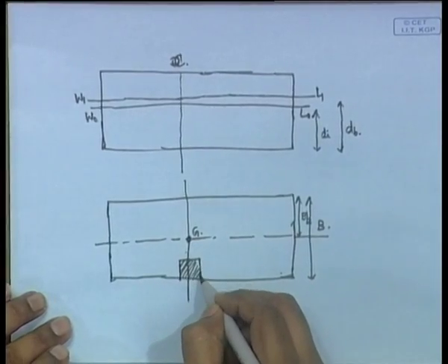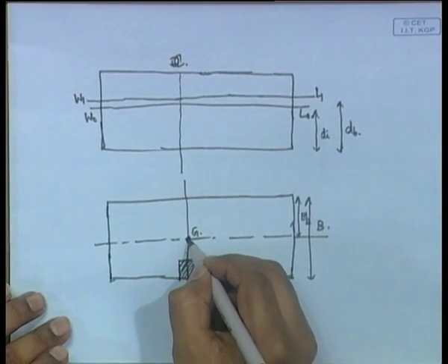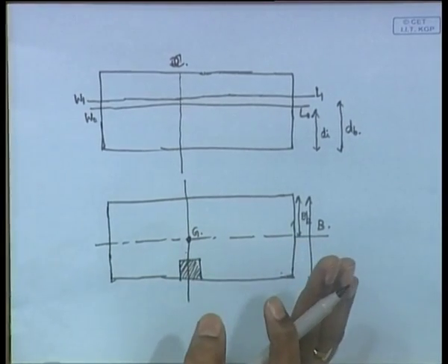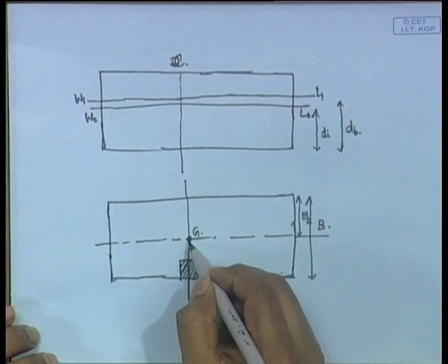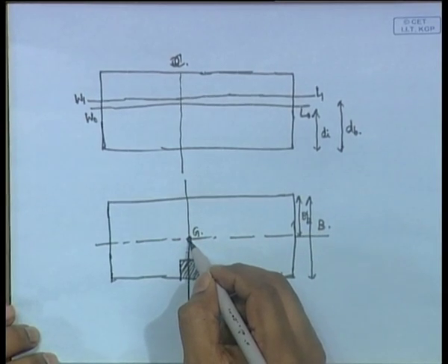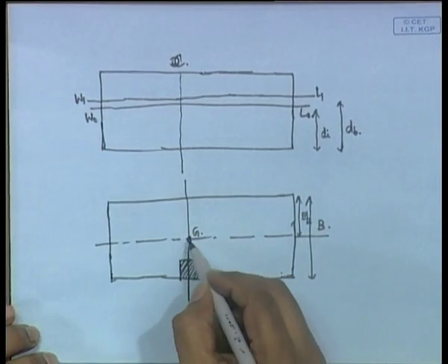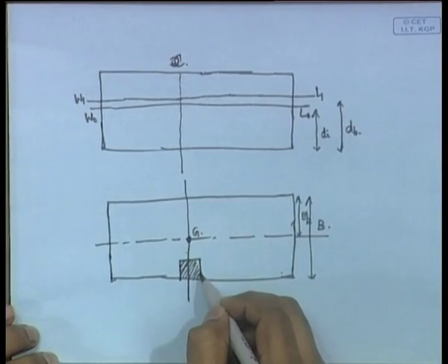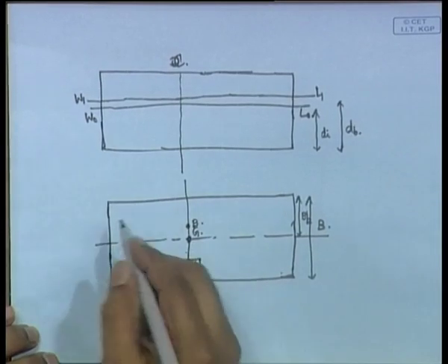So, this much volume is lost. Therefore, when the vessel was upright and had no bilging, G and B were in the middle. When you look at it in this top view, G and B were exactly in the middle, because volume here is equal to volume there, so you can assume that the volume is in the middle. But the moment this part gets bilged, some volume is lost here, and B moves here. B is somewhere here.